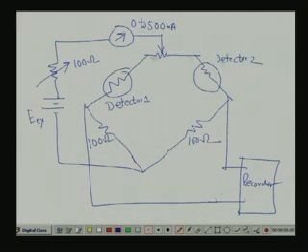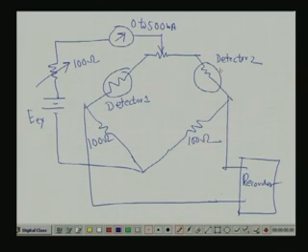Okay. So, the same carrier gas is passing through both the detectors. In both the cavities, that means we can have the same sensors also. Okay. So, it looks like this. You see, this is the thing. Let me first explain, then I will go to that. See, two detectors are there. The same carrier gas is passing through both the detectors, but there is no column or anything on detector 2. Initially, I will balance the bridge by varying this potentiometer.